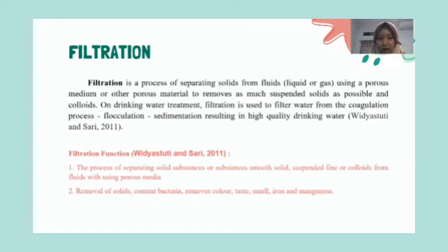Filtration functions are: number one, the process of separating solid substances, or fine suspended solids or colloids, from fluids using porous media. Number two, removal of solids containing bacteria, and removal of color, taste, smell, iron, and manganese.